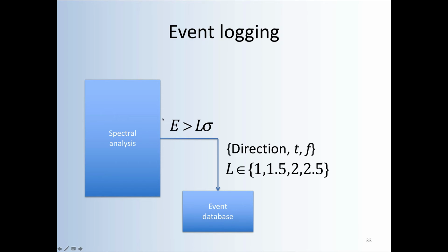So how would we discover such a signal? Well, we can do it in a fashion like this. We start by doing a spectral analysis, so we're looking at different frequencies, and then we're looking at the energy within certain short periods of time. This is called a short time Fourier analysis, looking at the energy within certain lengths of time at different frequencies.